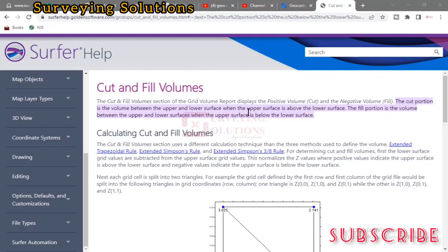Then you have a surface that has elevations from 15 to 20. What this cut and fill analysis does, making reference to that 17, is interpolate those elevations you are going to cut, which are above 17, and those elevations you are going to fill, which are below 17.